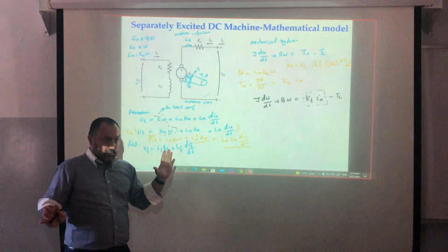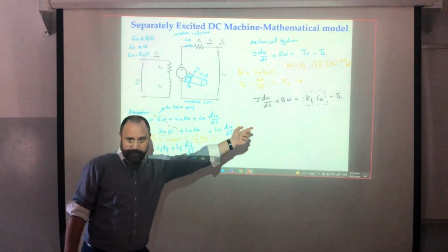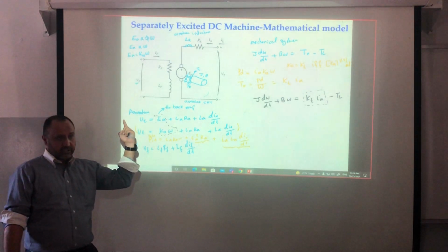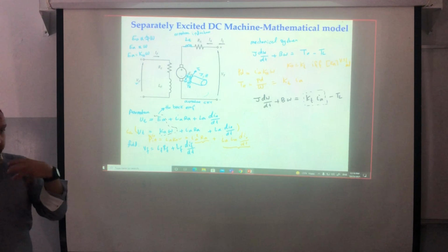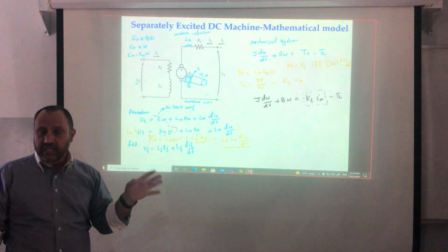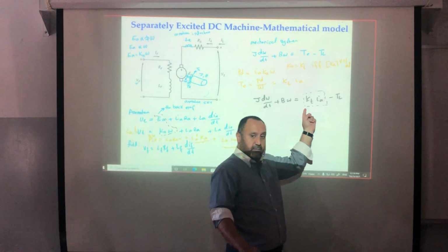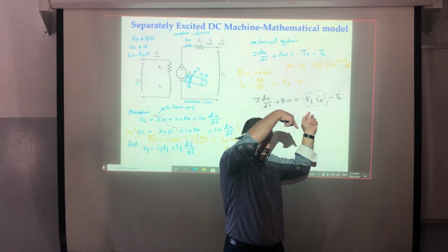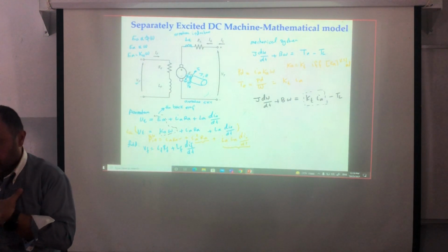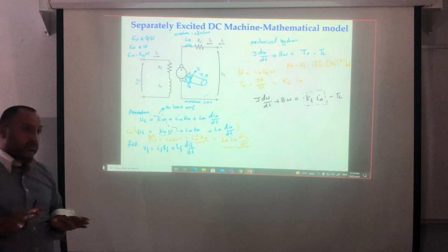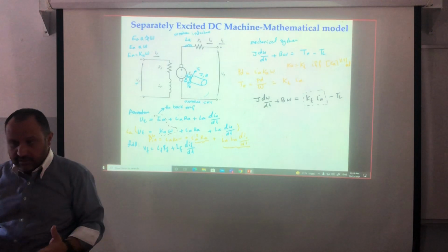So this one is the interaction between the mechanical and the electrical, which is the induced voltage, and this one must be maximized or be the key factor of the design if the machine is designed to be a generator. And this one is the coupling between the electrical and the mechanical, and this one must be maximized if I'm designing the machine to operate as a motor. And I told you that in the drive, all the time I'm interested in the machine as a motor. Good.